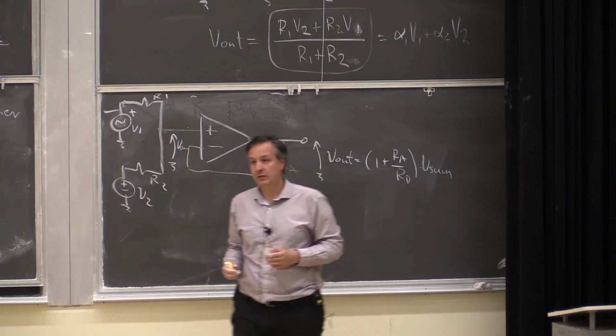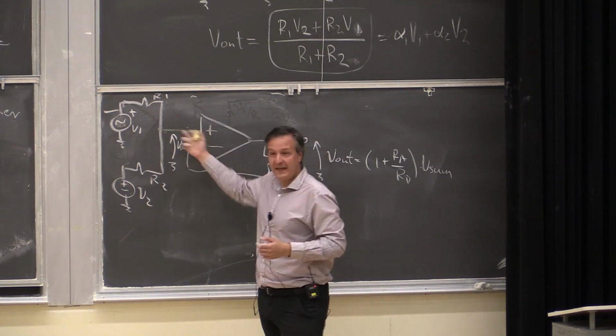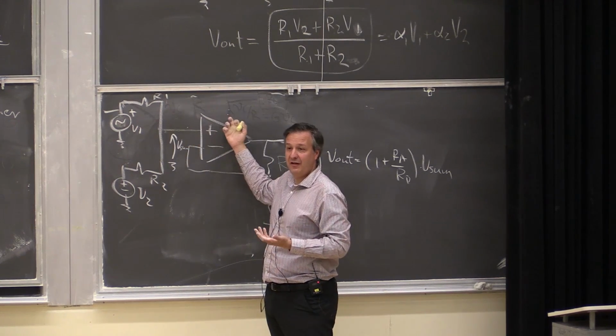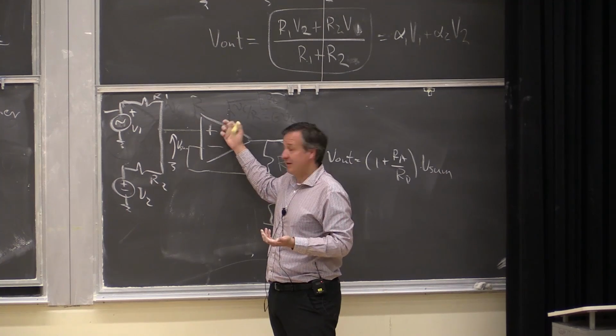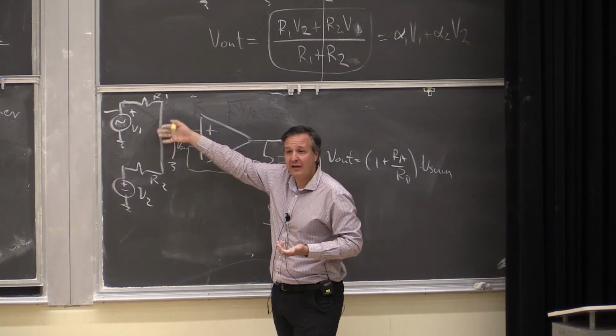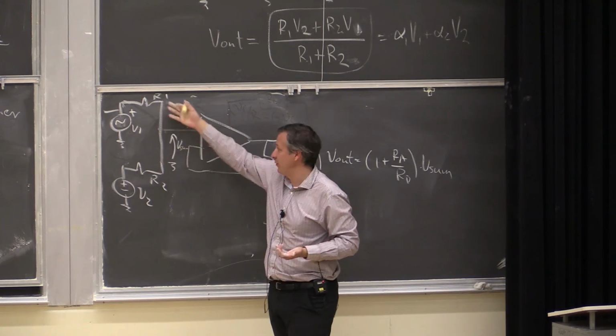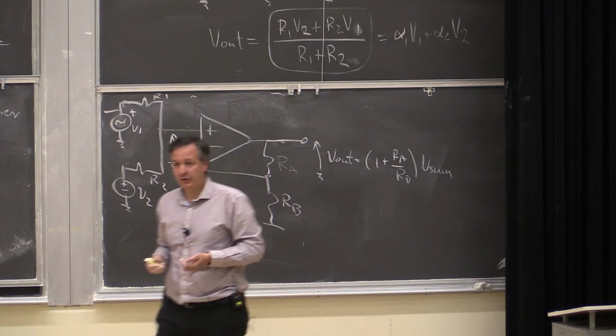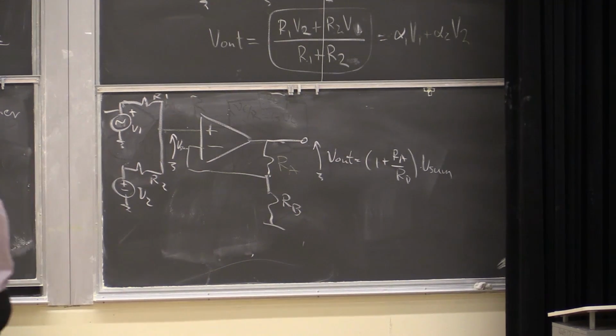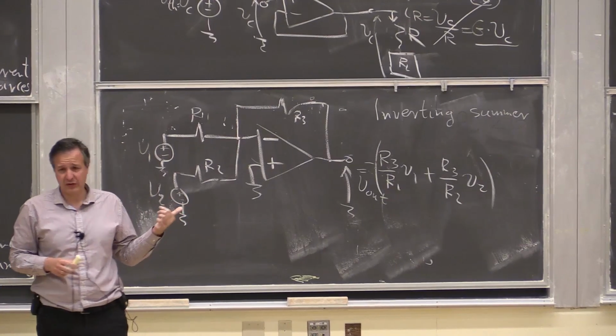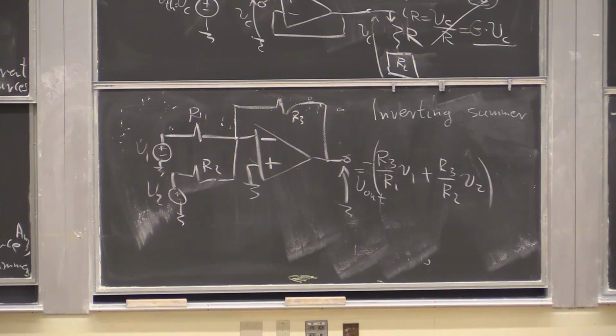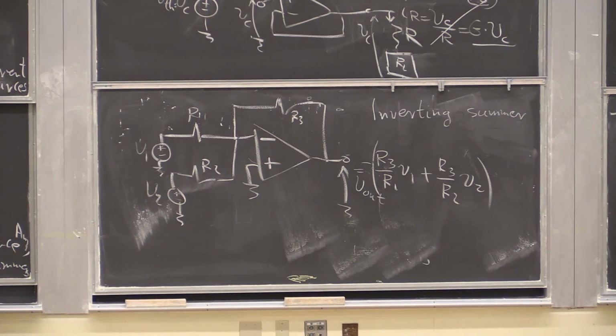Yeah, you don't need it. But then to use that signal, you will need at least a buffer, right? Because the moment you don't want to add any load to this circuit, it will disturb this voltage divider. Right? In fact, I think you're going to learn about level shifters today in discussion.